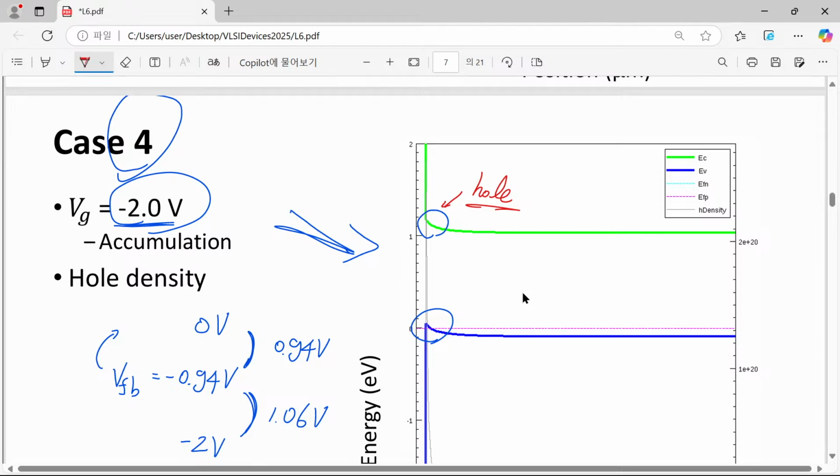I mean that when you apply gate voltage equal to 0 and gate voltage equal to 1 volt, and now additionally apply 0.001 volt, 1 millivolt, to your system, although it is the same system, when it is biased differently, these two systems already have different numbers of electrons in them.